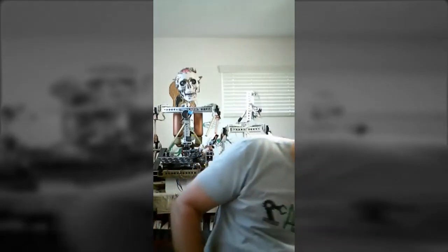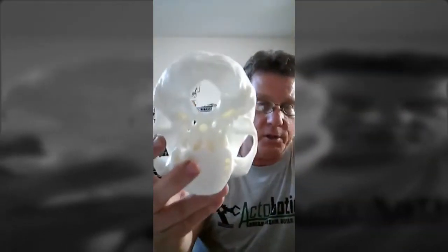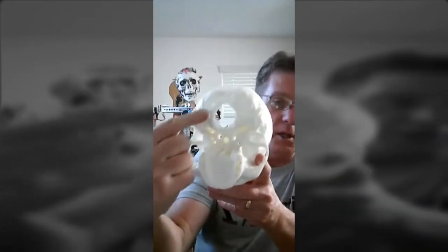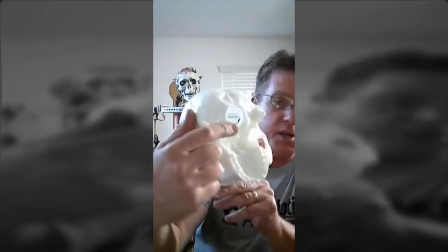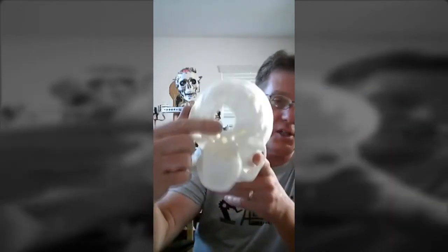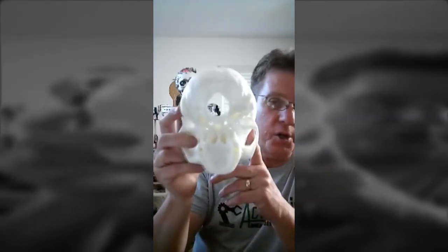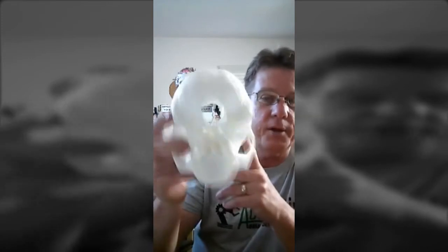Just one thing I do want to mention: if you're building yours for the first time, a Lindbergh skull has got a hole on it that big. You need to about double the size of this hole right here to be able to get nice movement so that none of the bars hit as this thing is tilting back and forth. So I think it takes a 2.5-inch hole saw. The biggest I had before was a 2-inch, so I had to go out and buy one.